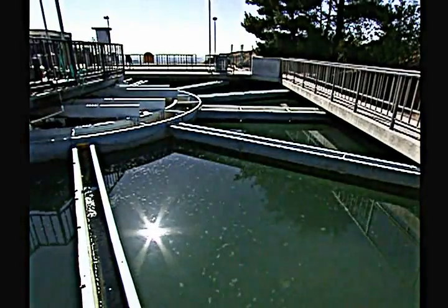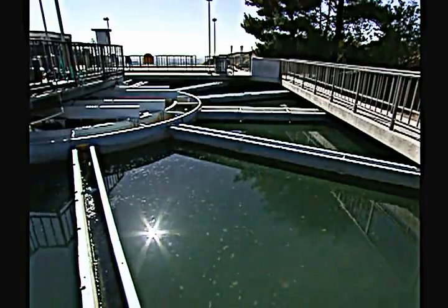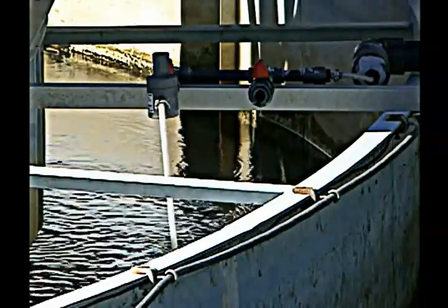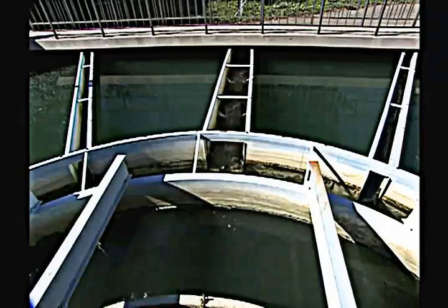Density currents can occur when the influent contains more suspended solids or a significant temperature gradient. The influent can either sink to the bottom where it creates upswells of sludge or rise to the top and bypass much of the basin. These problems can result in short-circuiting, which can result in water bypassing the normal flow path, reaching the outlet in less than the normal detention time. Floc-laden water can clog filters and interfere with the disinfection process.